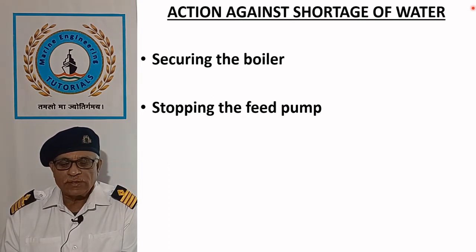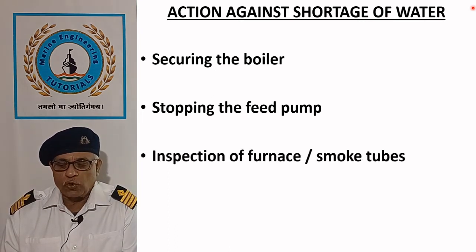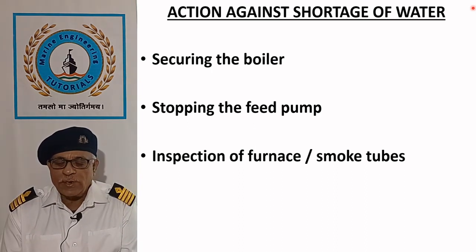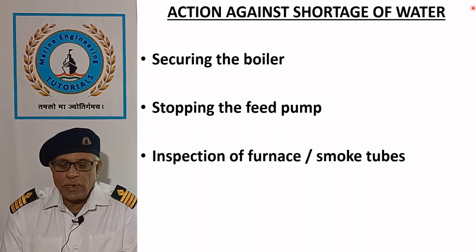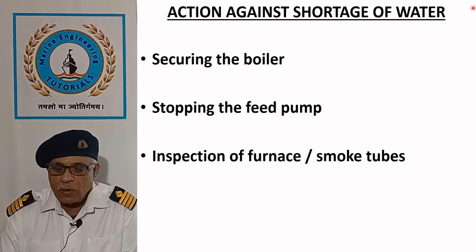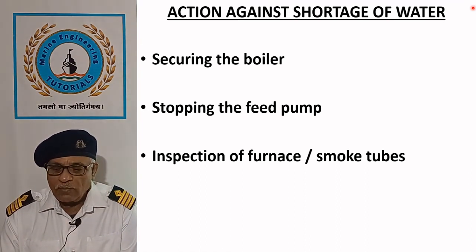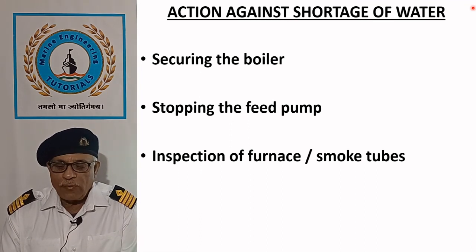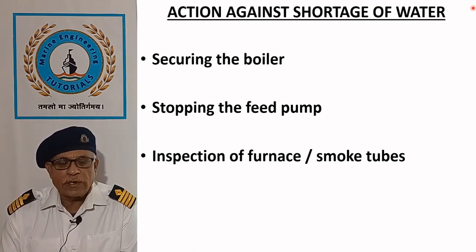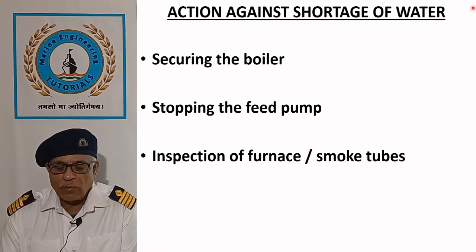Inspection of furnace or smoke tubes. Depending on the ship's arrangement, boiler should be preferably cooled down. This may not be possible on motor ships equipped with either a composite boiler or a single oil-fired boiler working in conjunction with a forced circulation exhaust gas boiler.